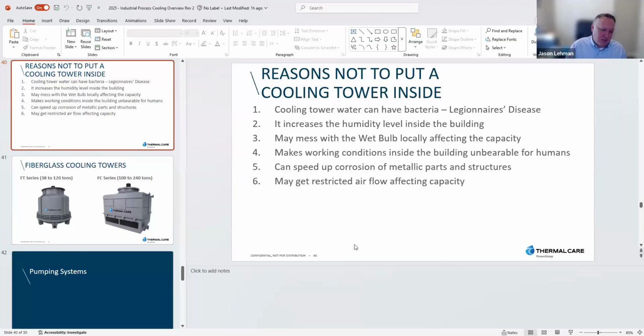Because you don't want to have compressors turn on, turn off, turn on, turn off, and that's how you burn up compressors. So you really want to allow for some stability coming in. And with your PID control, how precise can you get on your supply temperature?